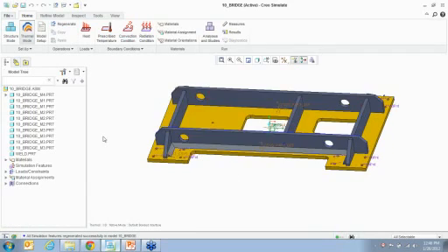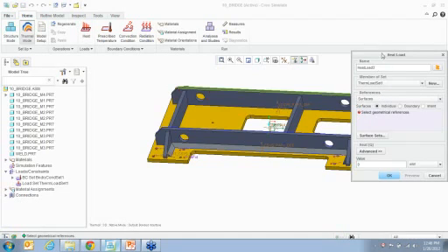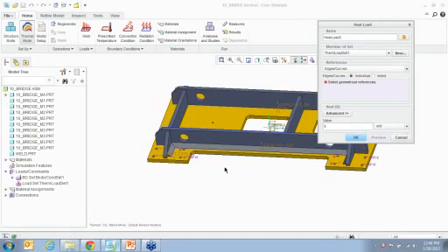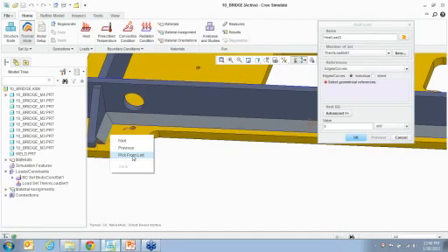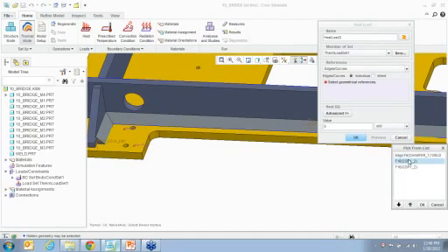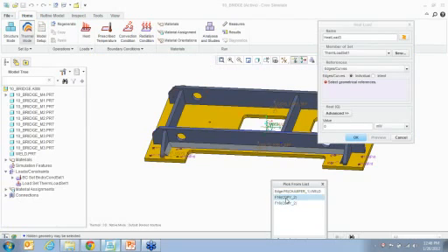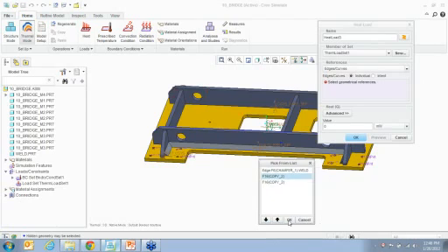So right here we are in the thermal mode. So you have all these boundary conditions set. So let's apply a heat load. Heat load on a curve. Now I can right click and pick from the list. Notice it highlights the whole curve in green right there. We can go ahead and pick them.